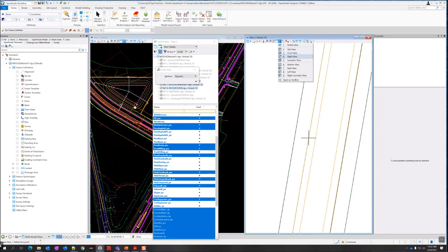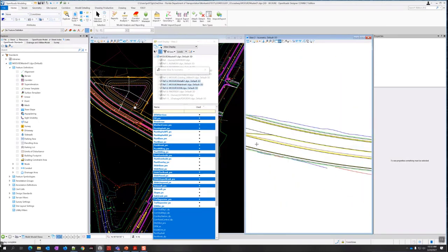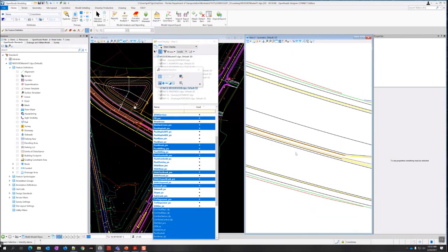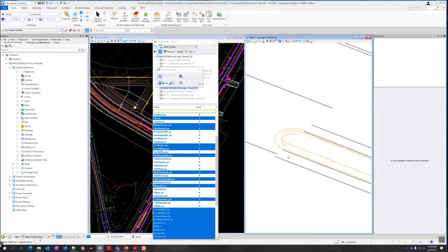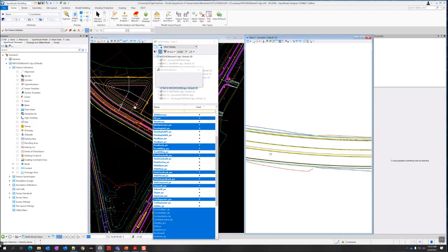So not an issue as long as you're not creating any vertical surfaces. And I think that was set purposely not to create any vertical surfaces. So that's just something you keep in mind for any of these. We're creating a DTM, so we have to have all its triangles and everything. If you create any vertical surfaces, you're going to cause an issue. So your templates have to be built so anything that's going to be in the proposed top or the proposed bottom surface is not creating a vertical line. If you just offset it by 0.01 in the templates, that should be sufficient.